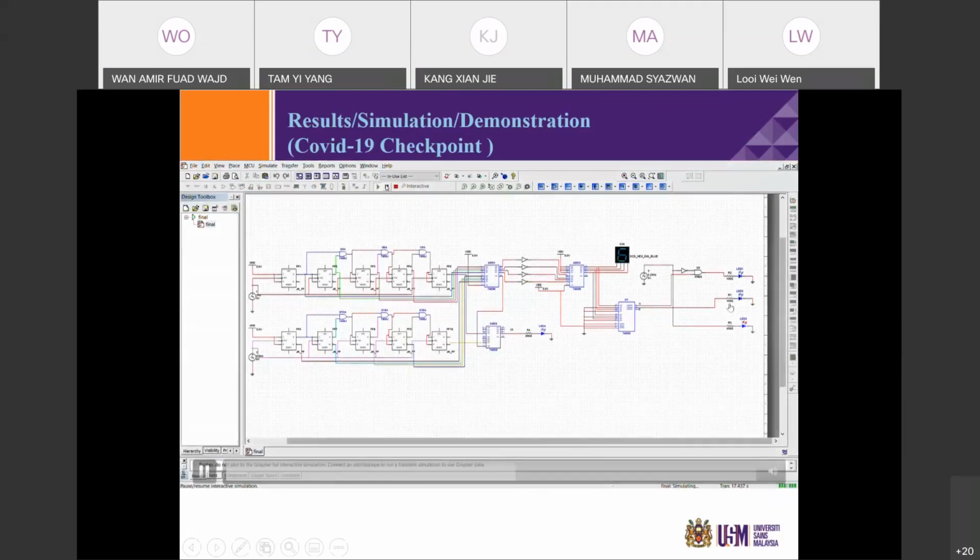And then we'll wait at the 7-segment display, when it counts to 0, which shows no seats available, the orange LED will light up here. Then after that, if the counter continues to count, it will exceed the limit. Therefore, the yellow LED will light up to show the error, and we need to reset it manually. Okay, next.